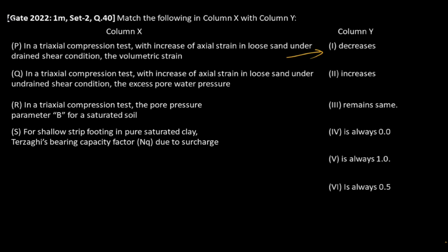Coming to the point Q, in a triaxial compression test with increase of axial strain in loose and undrained condition, since it is undrained condition, the excess pore water pressure will increase due to increase in axial load.